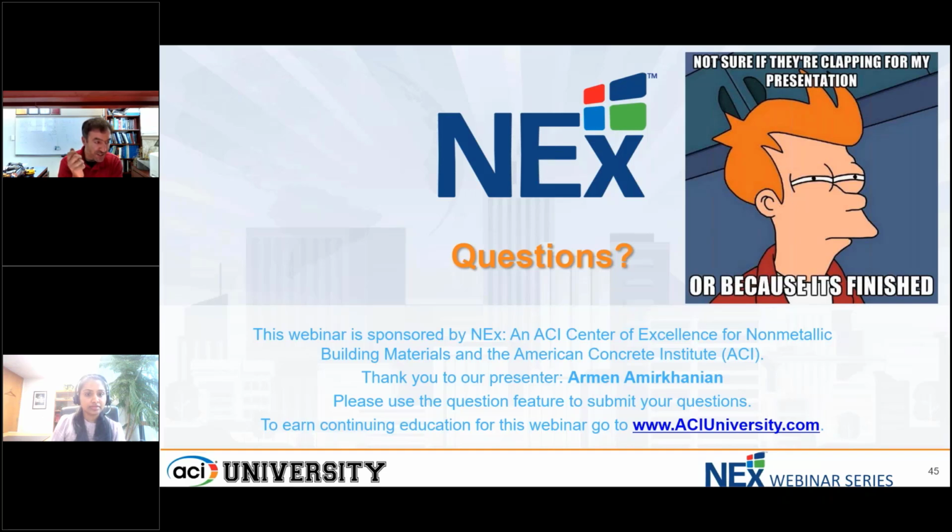They said, okay, it's really bad with 100% ASR-active sand, because that causes expansion everywhere. But concrete is pretty strong, so if it's only expanding in a little bit of it, it may still be able to withstand that internal stress and not crack. So very briefly, yes, I think you could dilute the badness of ASR by using a known non-reactive sand to help spread that out and not generate such high internal stresses.